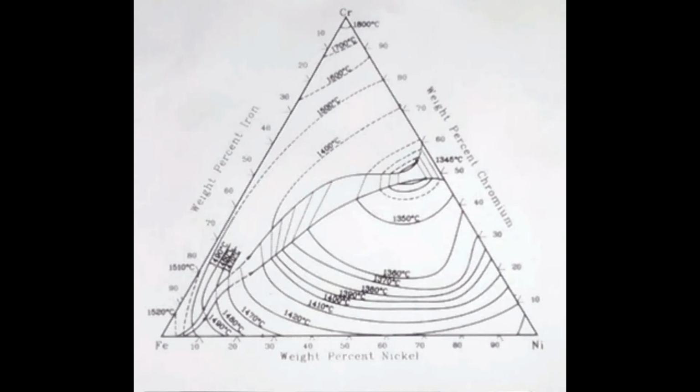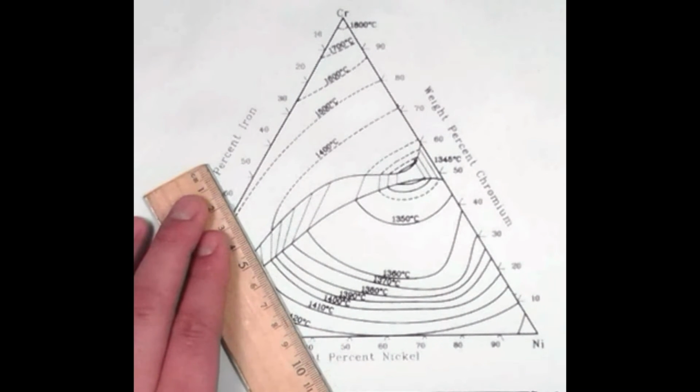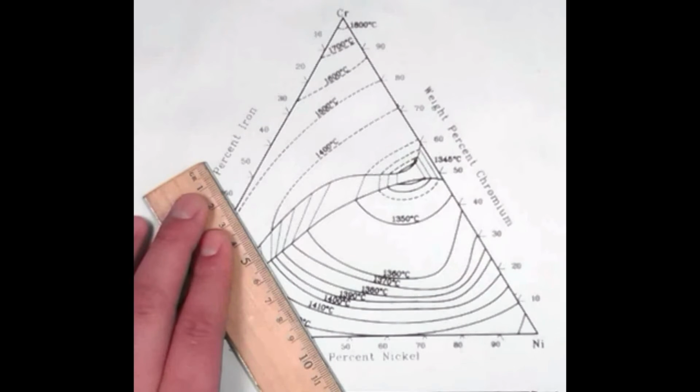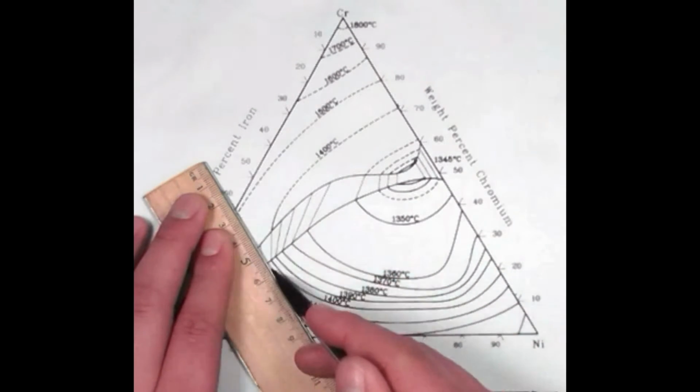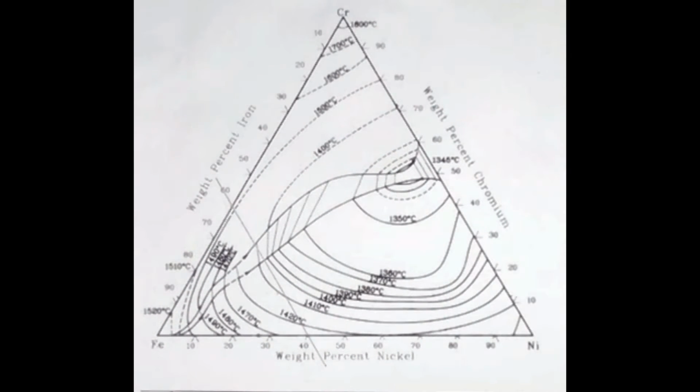Remembering that our composition will need to be 100%, and if we had 0% chromium, in turn we would have 40% nickel. By drawing an isocomposition line between the 60 and 40%, we will gain a parallel line from the opposite side of the triangle of iron. This would also be the case for our chromium.